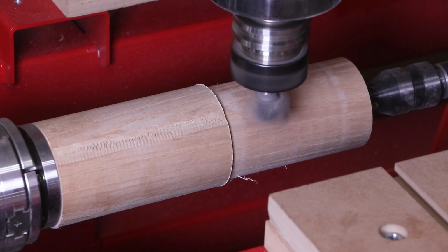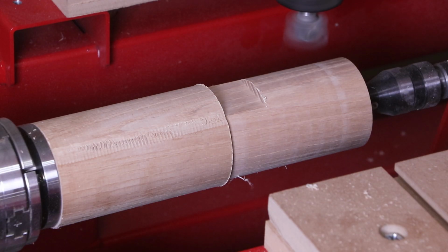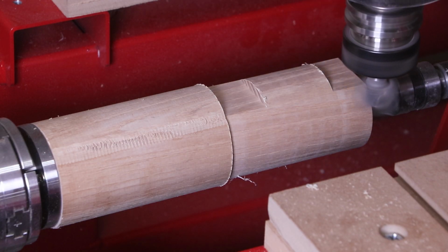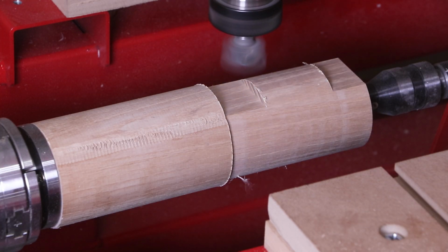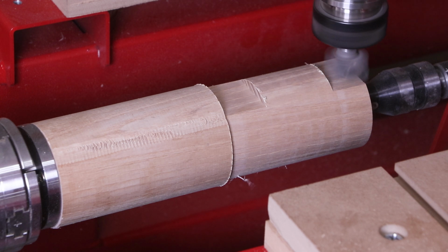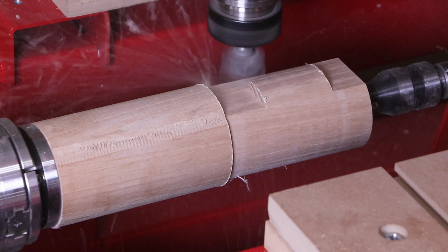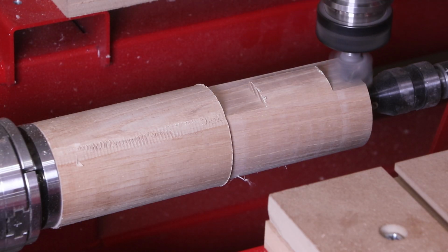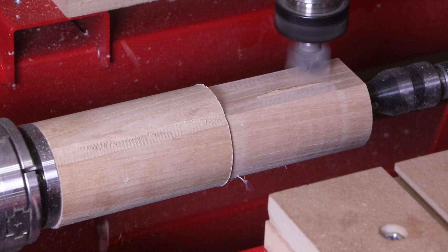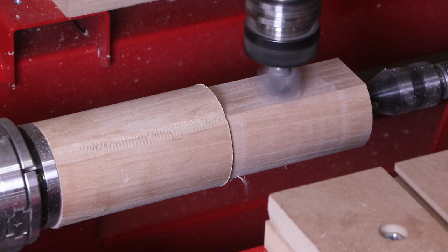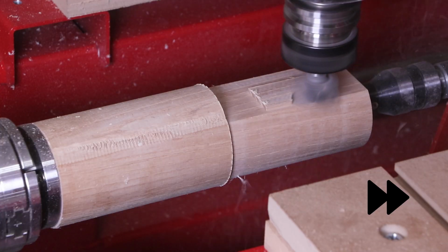Now the cutter approaches this cutting technique the exact same way as the multi-sided surfacing. It will climb mill the edges of the part first, going around the perimeter, and then work its way in towards the center. The difference is that this stock is beginning from a round cylinder diameter, and it's going to have to remove a little bit more material, so it's going to break this up into 2 passes for each surface. You may notice that all of the x-axis cuts that go along the length of the spindle are climb milled. This ensures that we get the best cut quality possible with minimum sanding.